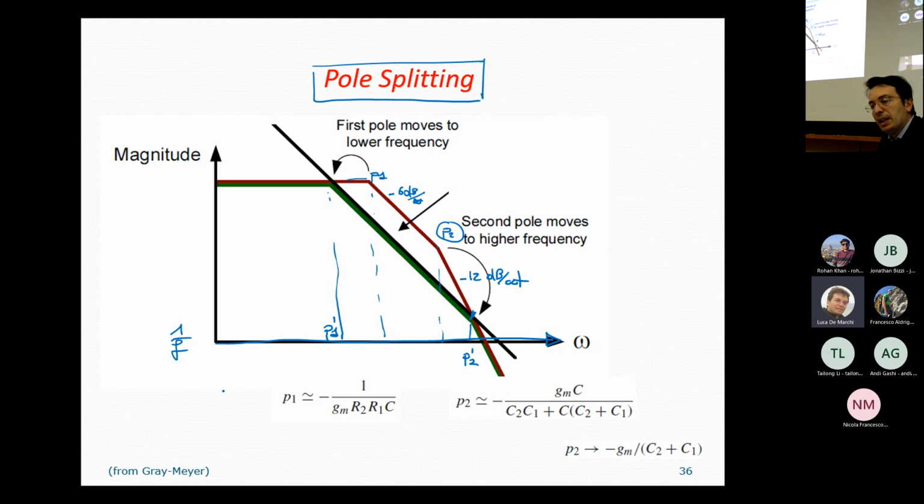So the differential pair gain is, as you may remember, GM over the intrinsic output conductance of this transistor, which is transistor number 2, and the intrinsic output conductance of transistor number 4. And this GM is the transconductance of the element of the differential pair.